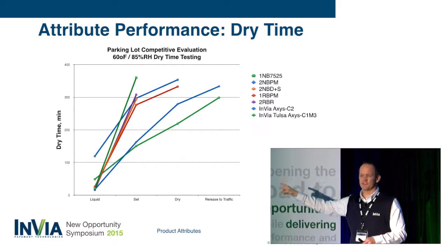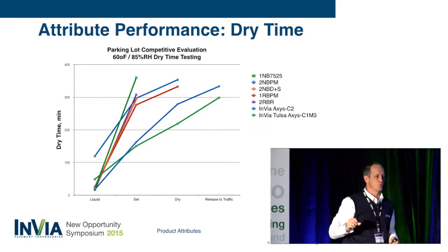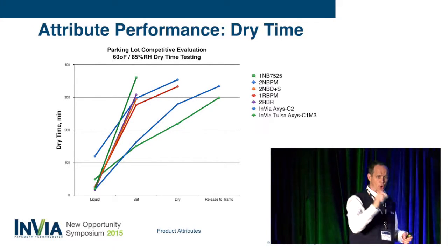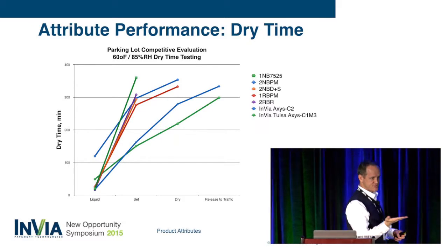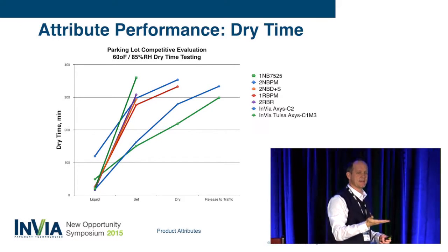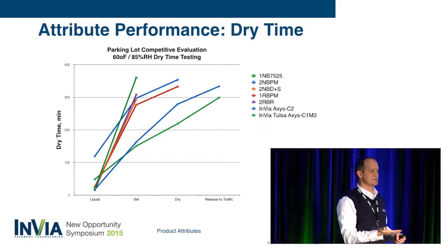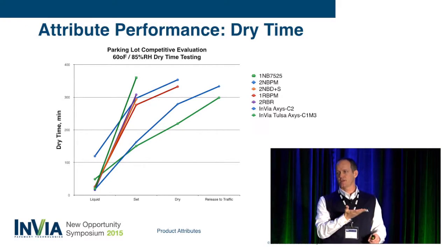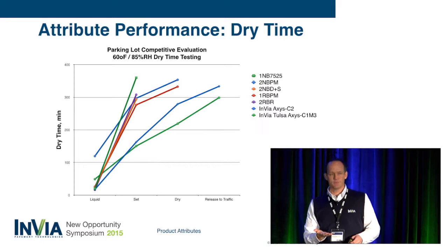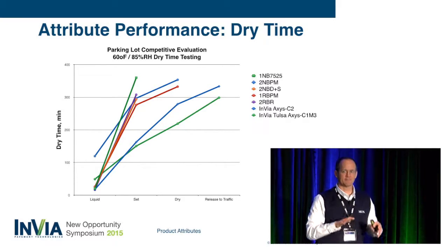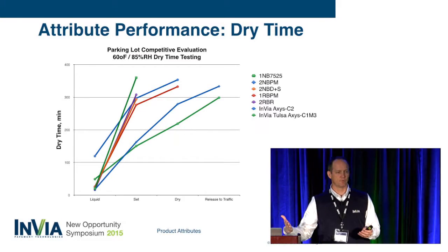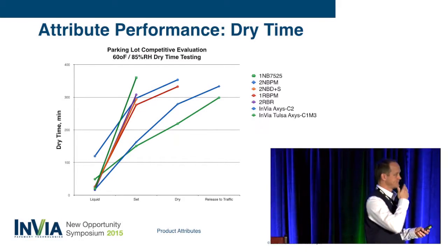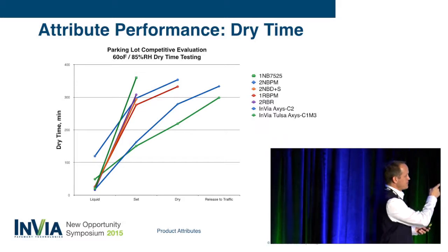The other thing about this is it's in an environmentally controlled oven, which means it's dark, there's no sun, so the pavement, or the surrogate for the pavement, temperature is identical to the ambient. So you have 60 degrees on the pavement, 60 degrees in the air, 85% humidity, and then Tim went to great lengths to build a chamber around it so that the air wouldn't even flow through the chamber. So this is also zero wind speed. We're pretty proud of our performance.